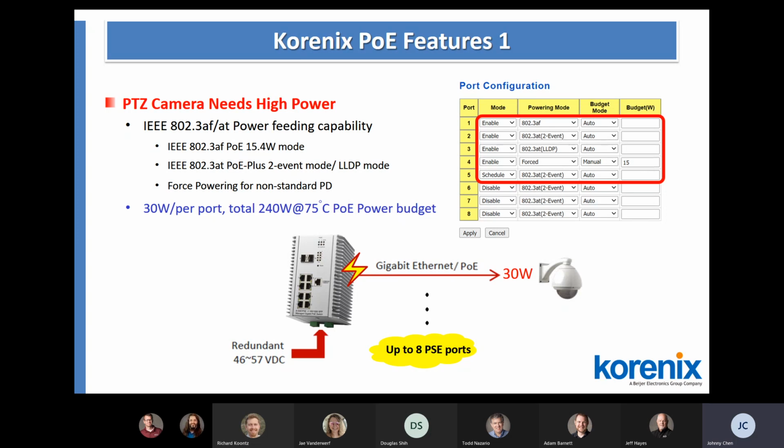And we not only support standard PoE devices, we can also provide power for non-standard PDs. So we have the AF mode and the AT mode, and also we have the force mode.